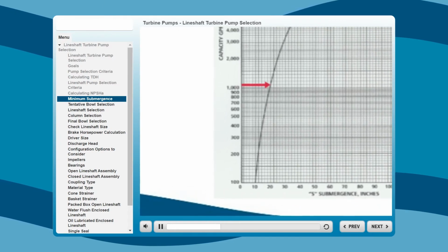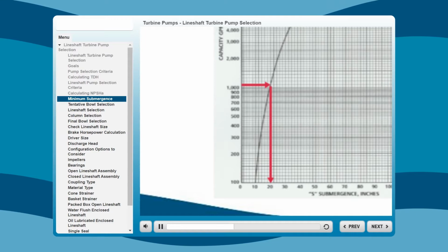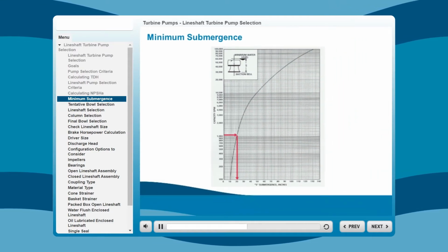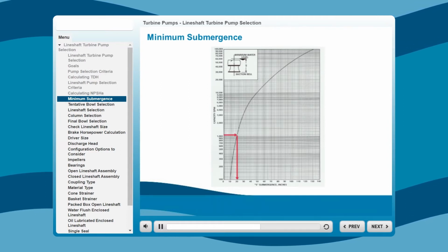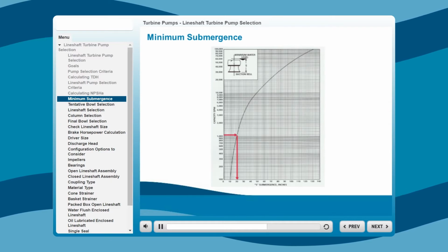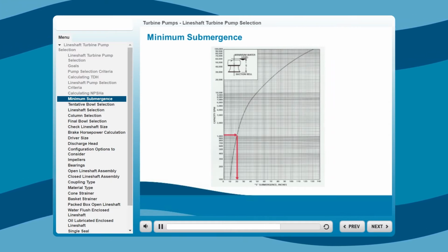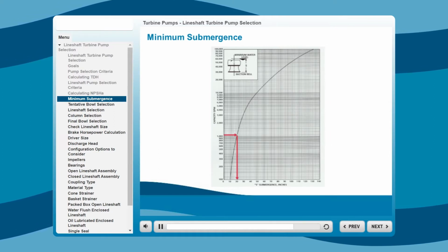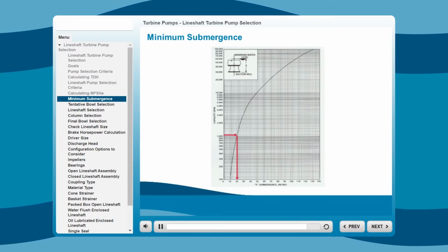There is a relationship between the intake velocity at the suction intake and the submergence, or S, of the intake. Minimum submergence is based on 2 times the bell distance between pump center lines and other ideal flow conditions. Refer to the latest HI standard on intake design or consult the factory for more information regarding your installation. Less than ideal conditions will require additional submergence. Make sure that your installation has the appropriate amount of submergence to avoid cavitation.